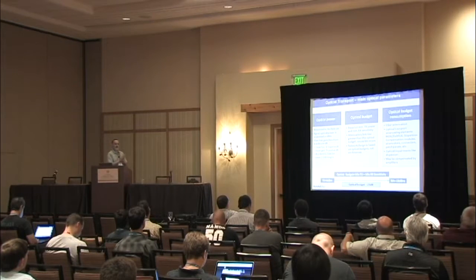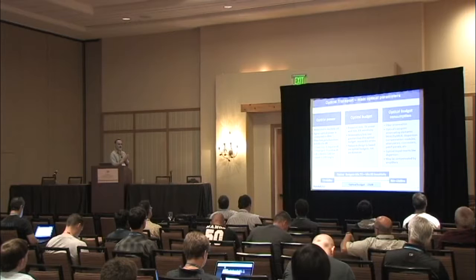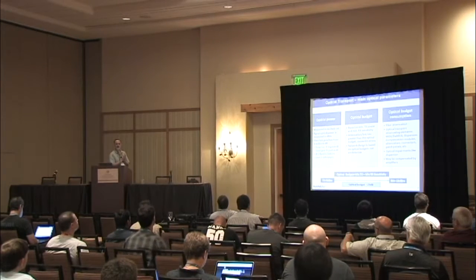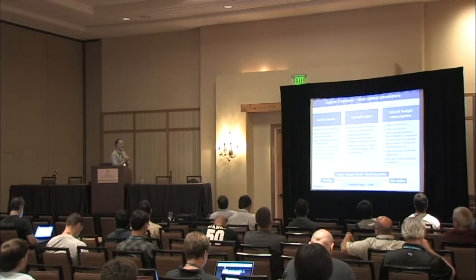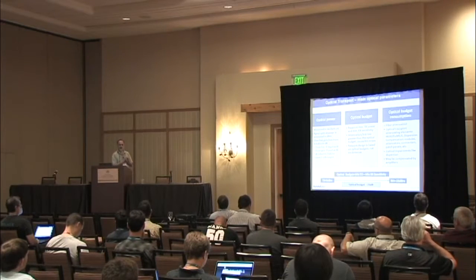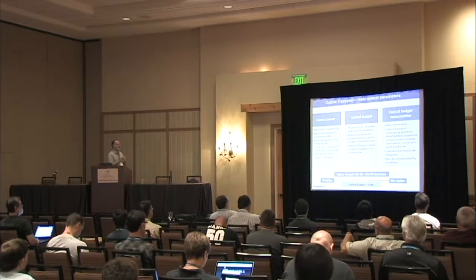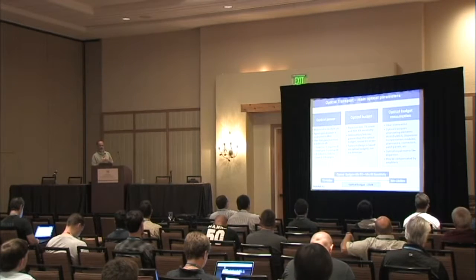If your link basically generates attenuation beyond this optical budget, you are prone to have errors. And in general, network design is not based on distance. It's based on measuring your optical budget and requirements of your fiber. Now, who are the consumers of this optical budget?